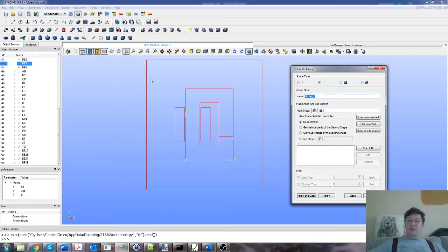Let's just suppose it's a bar of germanium heated at one end, in 2D, and I wanted to put a heat flux on one of the edges. I'd need to make sure I had access to that. I don't need to put any magnetic current density on any of these lines. I'm going to put it on this face, but since I haven't made the faces yet, I don't need to make groups for that. So I'm pretty sure I only need to group this outer set of lines, because I do know that I'm going to have to put an infinite boundary on there later to keep all the flux in.